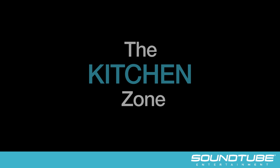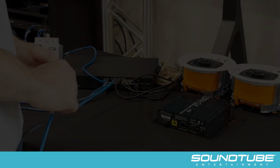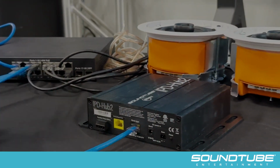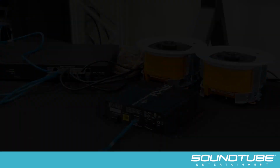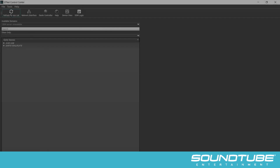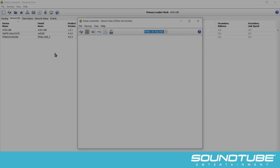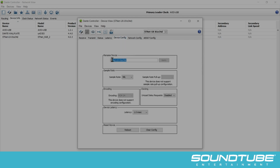We will start with the kitchen zone. First, we will connect an IPD-Hub 2 to the switch using an Ethernet cable. Once connected, we will see in the SoundTube STNet Control Center software that the device is appearing in the device list. We can then switch over to Dante Controller, click on the Device Info tab, double-click our new device, and then click Device Config. Here we can rename the device so that it's easier to keep track of each one as more are added.